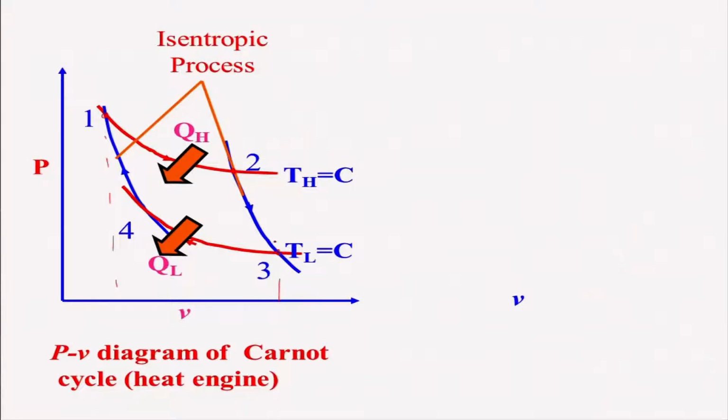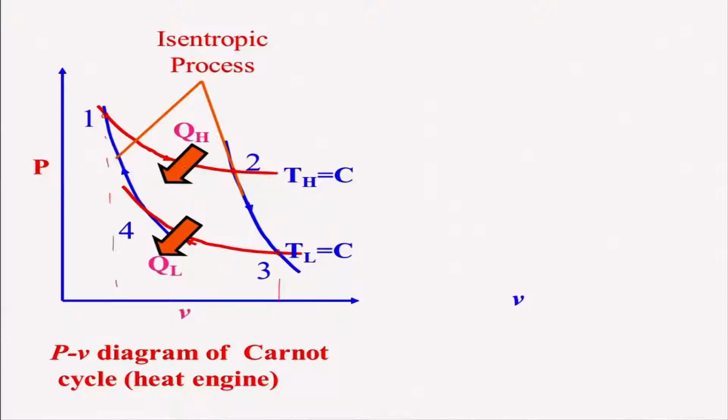Now, I say look, it is a reversible process. Instead of here in this process, can I not go back here? If I go back here, what will happen? This work will be nullified. So, therefore, we need to take this from state 3 to state 4, that is your isothermal compression process, in which the system will be giving a certain amount of heat to the sink, that is QL,